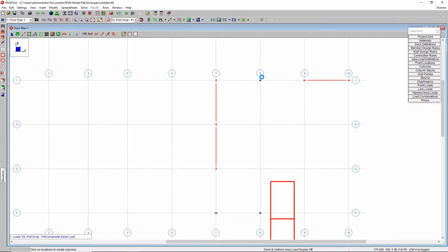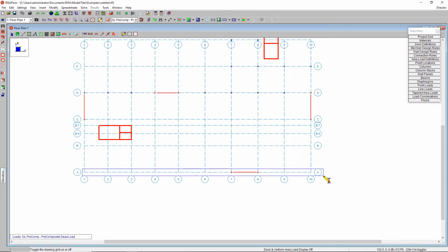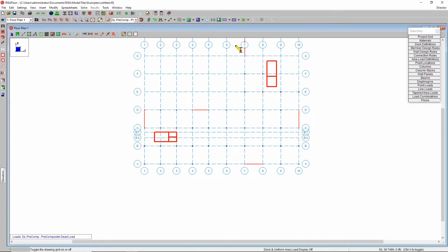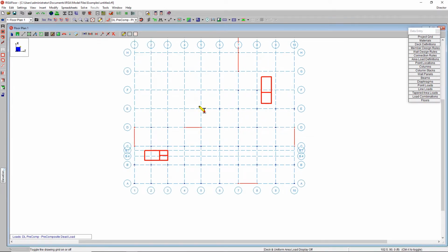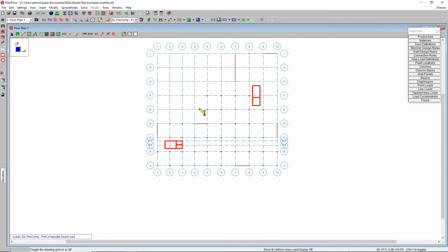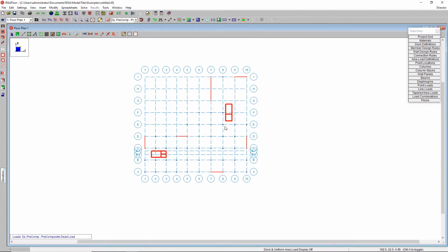So I'm going to go ahead and turn off my grid below there. There we go. And I'm going to just rubber band all across to create more and more columns. I have almost everything laid out. This structure is an L-shaped structure, but what makes it more interesting is I've got a few columns here in the center that make this foyer area flush out a bit. We're going to see that column line F is going to be shown here, and we're going to see a little bit more of that step out around that structure. So let me go ahead and just delete this one column out there. There we go. For the rest of the structure, we'll then draw our beam system in there too.